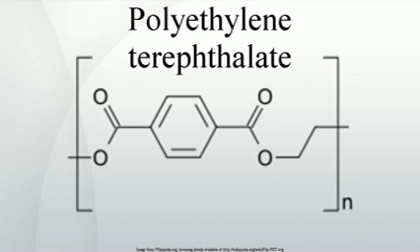The particle size distribution of impurities is very wide. The big particles of 60 to 1000 microns, which are visible by naked eye and easy to filter, represent the lesser evil, since their total surface is relatively small and the degradation speed is therefore lower. The influence of the microscopic particles, which, because they are many, increase the frequency of defects in the polymer, is comparably bigger. The motto "What the eye does not see the heart cannot grieve over" is considered to be very important in many recycling processes. Therefore, besides efficient sorting, the removal of visible impurity particles by melt filtration processes plays a particular part.